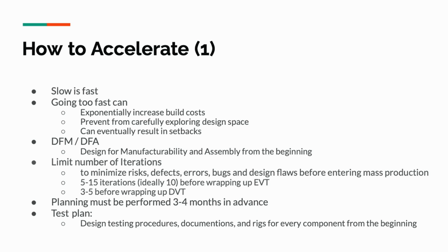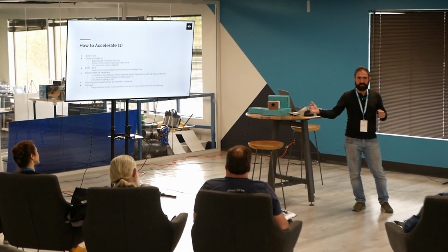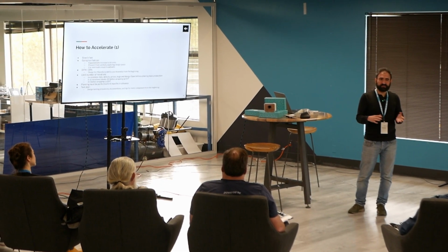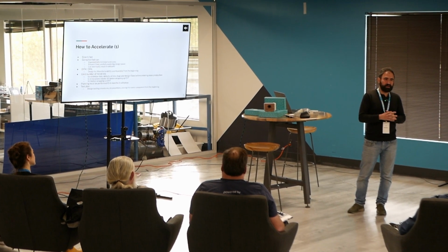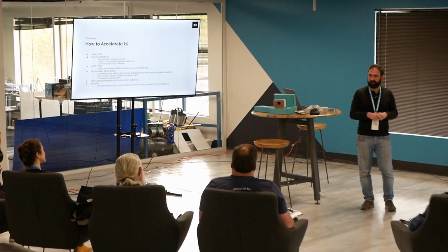With production, you have to think about next year, because injection molding is going to be 60 days, 2 months to wait for the mold, and another month to get your samples. So you're looking at very long lead times, and there's not really much you can do. You can insist on making things faster, but it's not going to happen.